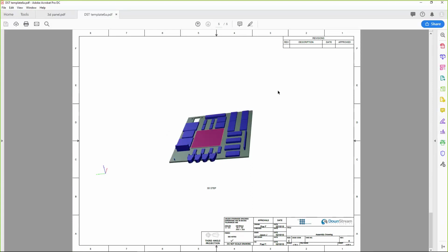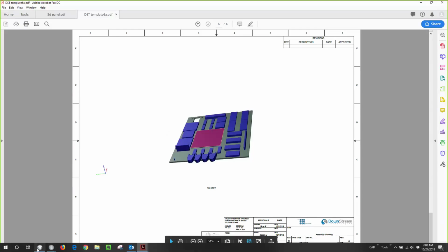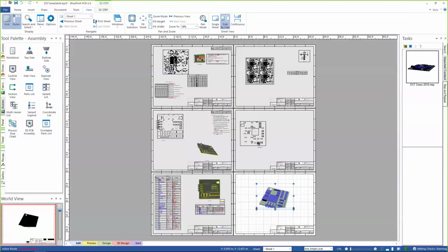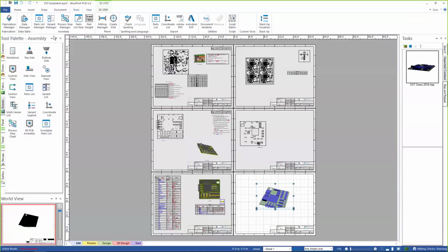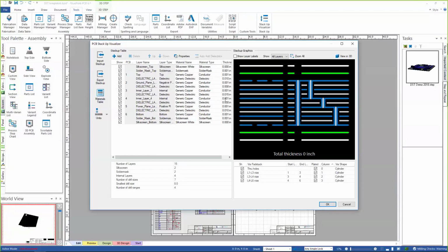Okay. So just to recap on the blueprint side, the main changes are the Stackup visualizer, being able to communicate back and forth with Stackup information. And also there's some nice things in here like being able to show the layer names as you're working on them. That's in both tools. And being able to change the dielectrics.